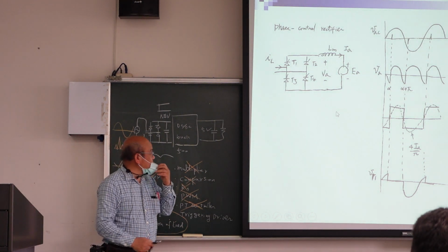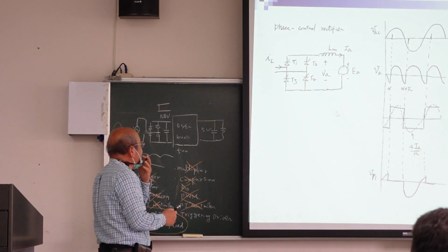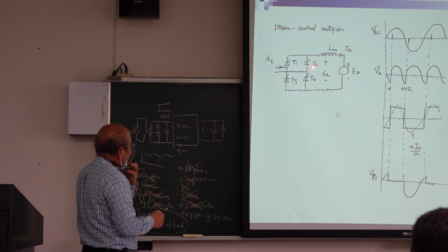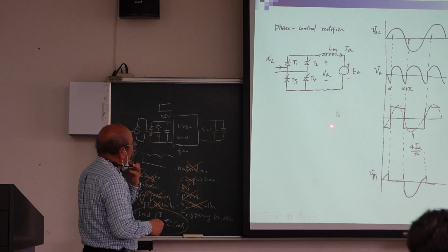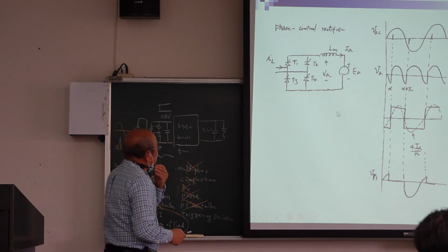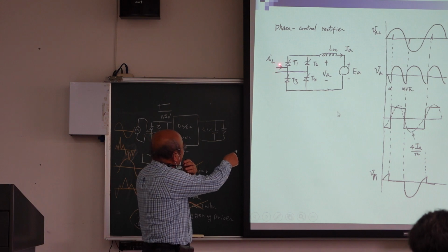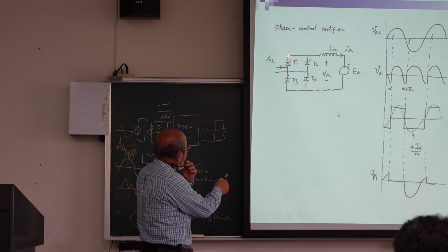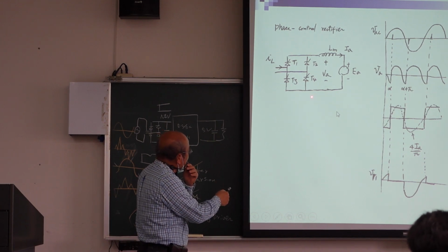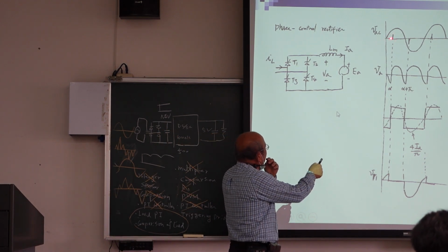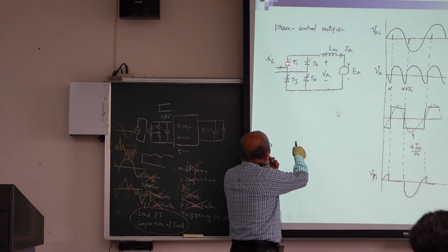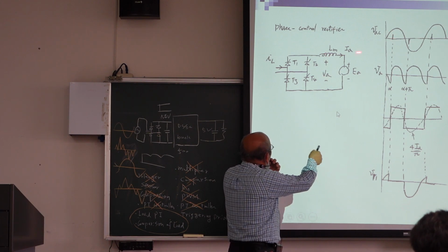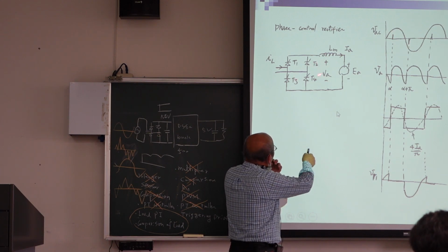So how about phase control? If we have MRT system, if we have elevator, what can we do for power factor correction? Then you can say we have AC input. So we call this SCR, SCR, SCR, SCR. We can control the delay angle. So we trigger the SCR for T1 and T4, and we trigger the SCR for T2 and T3.